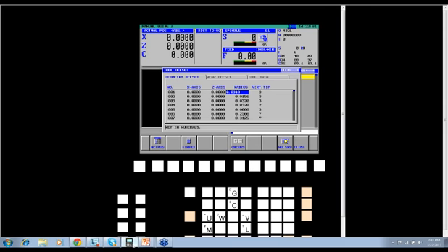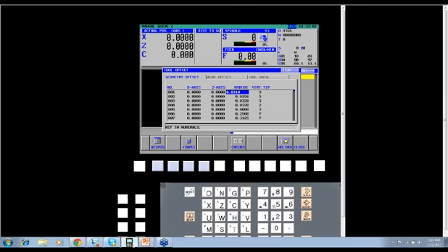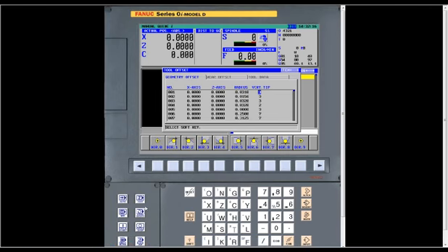The next one's very important also, the virtual tip, because what that's used for is the orientation of the tool. The ones you're going to use the most: a number 3 is typically going to be an OD turning tool. A number 2 will be an ID boring bar. A number 7 will be a drill. Those are going to be the 3 that you use the most. That's what you see on this first page, tools 1 through 7. We have a 3, 3, 3, 2, a 3, and then 2, 7. So typically, that's what you want there.